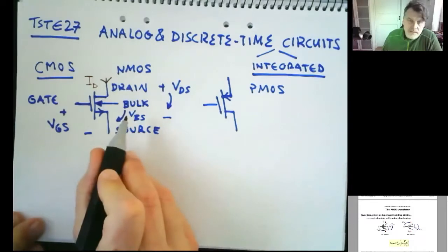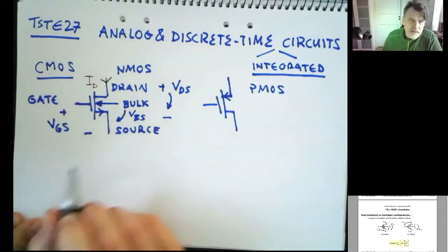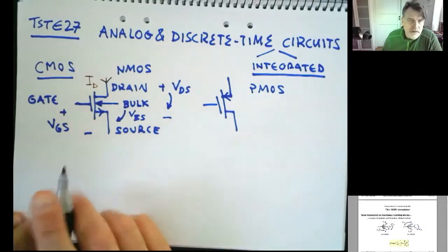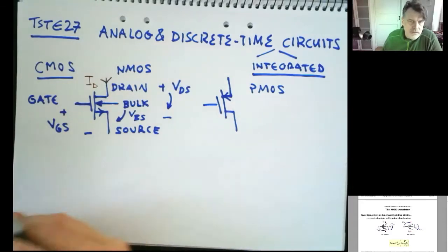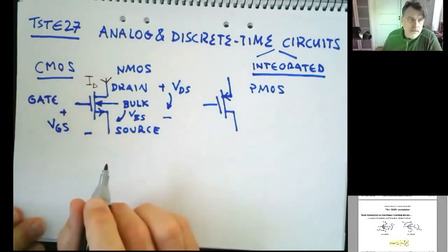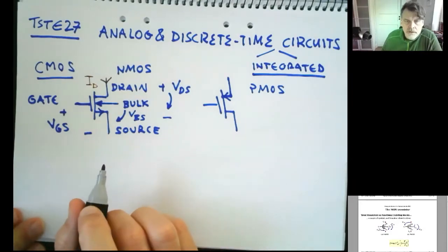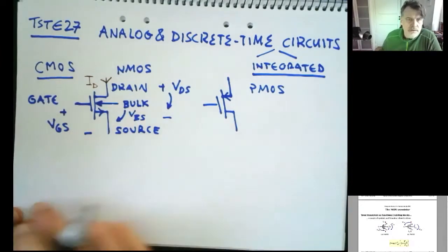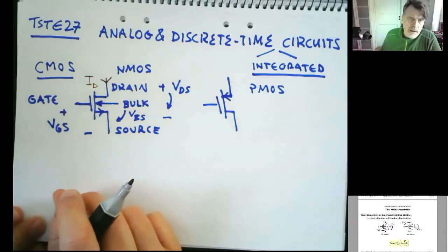And the other thing is we can quite often see that the effect of the bulk voltage is just a constant that affects your transconductance, your gain of your transistor. And then as a good engineer, i.e. lazy engineer, we just embed that constant in the expression and say, we just add a gamma or whatever.